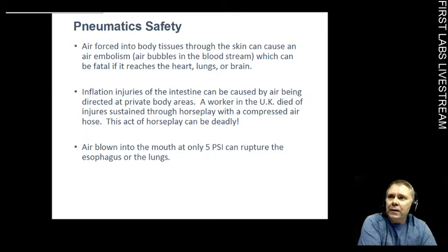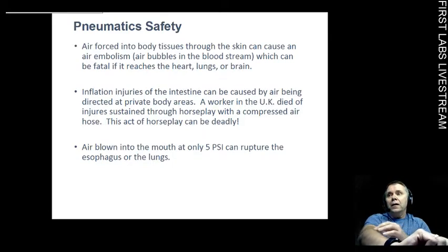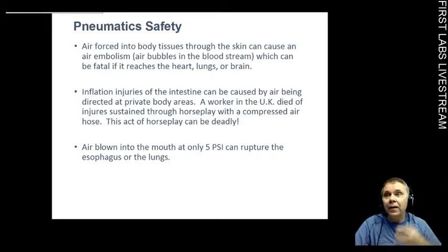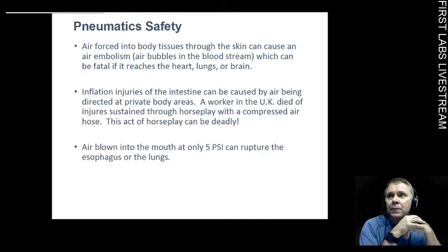Now, here's a little blurb on pneumatic safety itself. Air forced through the skin can cause air embolisms. You can have air actually go inside your blood vessels, and these can transit through your system into your heart, into your brain. It can cause strokes. It can cause all kinds of horrible, horrible problems, including death.